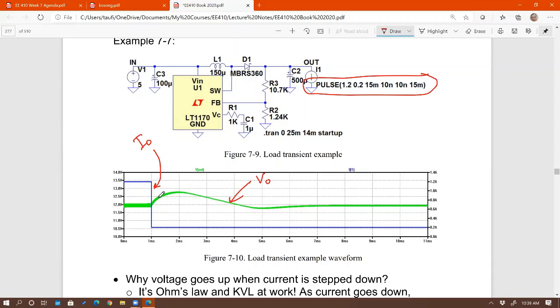As you are stepping down the current, the controller reacts. This feedback right here reacts to it, and then luckily it's stable. That's steady state, so it's stable. It's good. That's called what? Percent overshoot. Remember that? That's also called settling time. Now it's all coming back, right? Now you actually get to use those things that you learned from 302, percent overshoot, settling time.